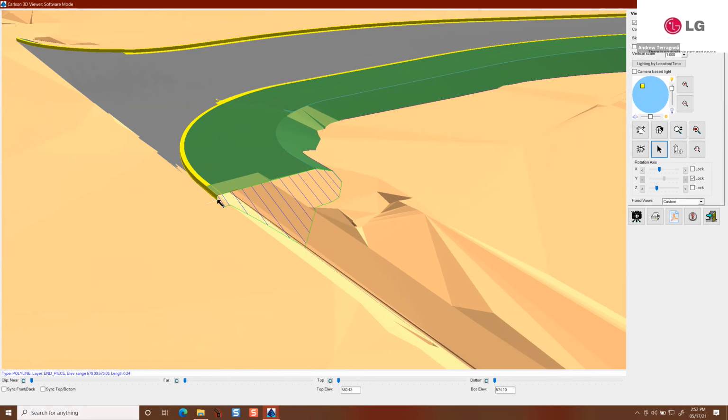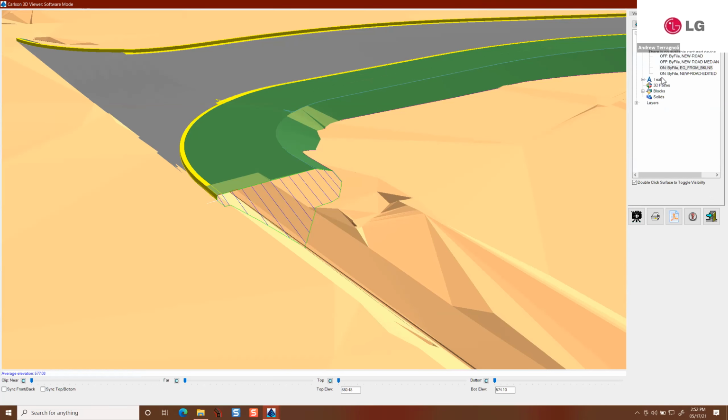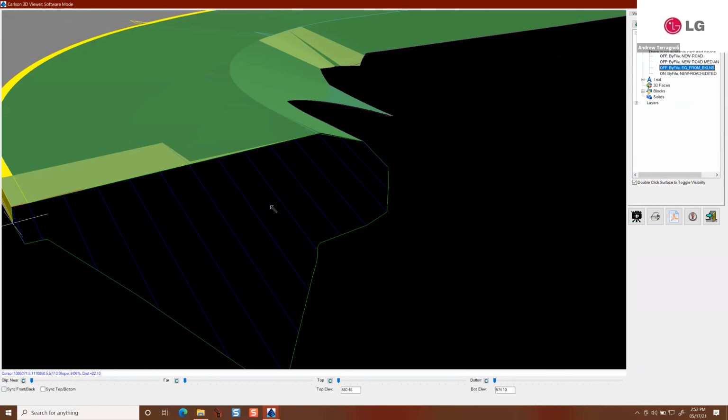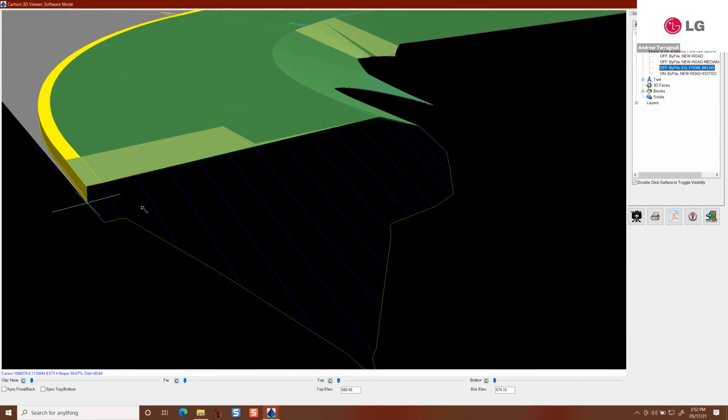And all I did was I took a 3D polyline and went, because these are the ends of all of these other 3D lines that are sticking out, and we just projected down with a pad command, right? Exactly right, a little similar to the median, not exactly like the median. We used TIN utilities for the median.